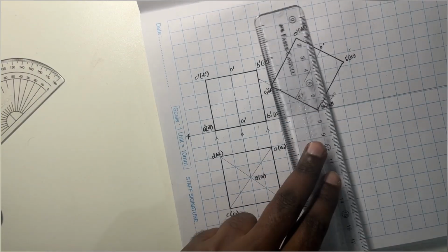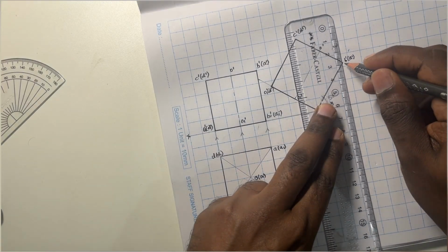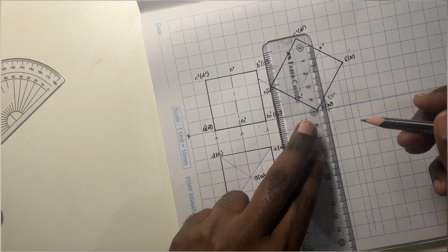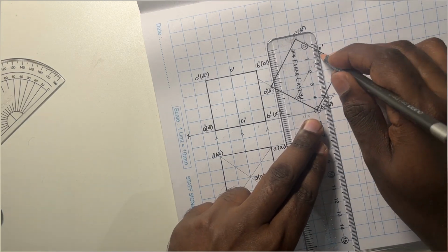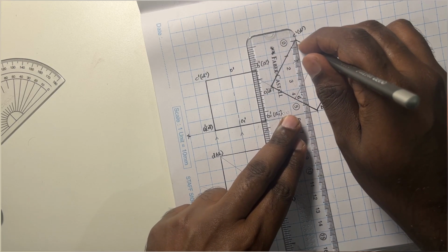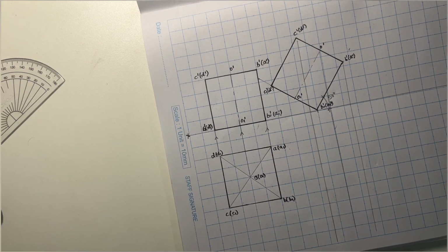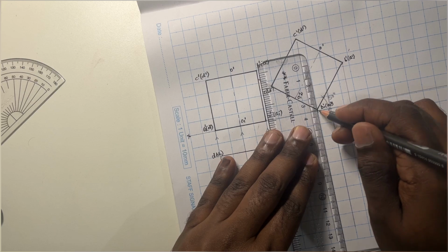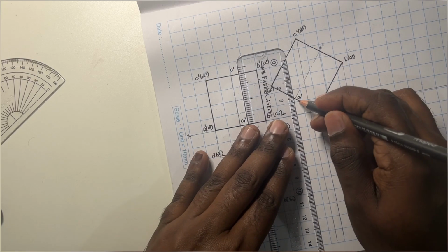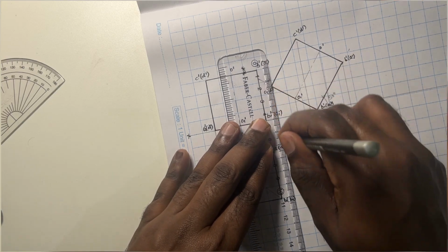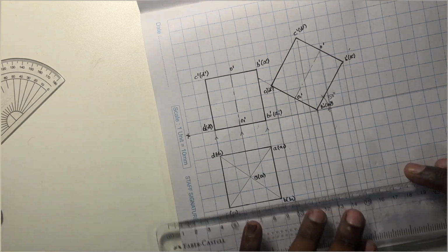Now let us proceed towards drawing the top view of the second position. So for that we require the horizontal projection lines and the vertical projection lines. So let me complete the vertical projection lines first. So this is one from B dash and A dash, and the next one is from O dash, and next is from the corners C and D. So ensure all these are exactly straight lines. And next we'll take the bottom face of the cube, that is B1 and A1, draw the projection lines, and from O dash draw the projection line, and also from C1 and D1 draw the projection lines.